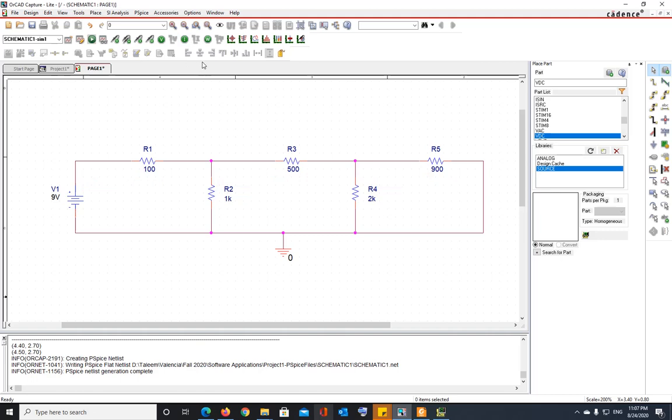And the last thing is how much power is dissipated in each source. So we are calculating power dissipated, not power supplied. Resistance always dissipates power, consumes power. So observe 2.51 milliwatt in this resistor, 57.27 milliwatt in this, in R4, this is in R5. All of them are positive, because again these are power dissipated.